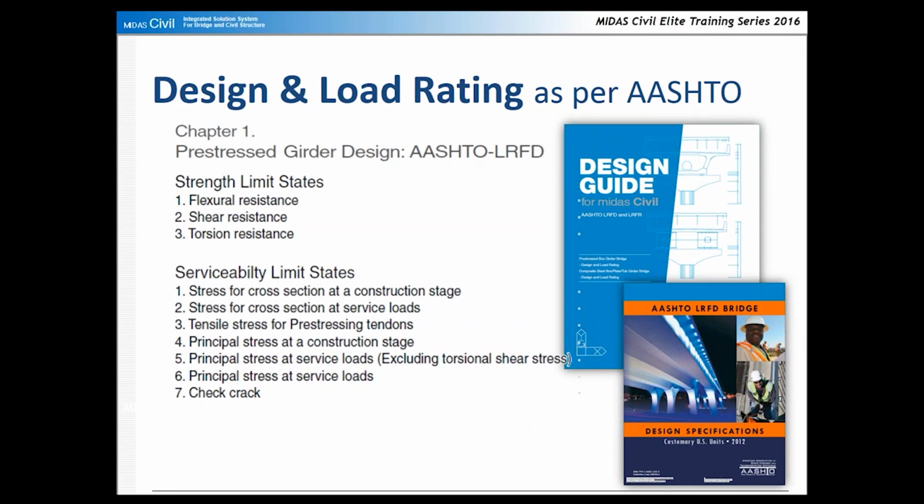You can see an overview of the checking parameters about the flexural, shear, torsion for the strength, serviceability. You can actually check the stress for the cross-section at the construction stage or at service loads, and tensile stress for pre-stressing tendons, principal stress at construction stages or the service loads, and also you can check crack.